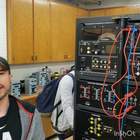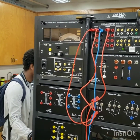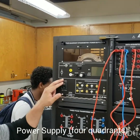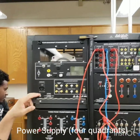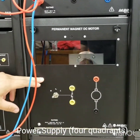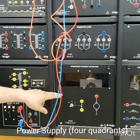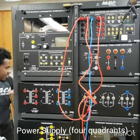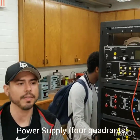My name is Enrique, working on the project with the EE350, and we're going to talk about the 4-quadrant dynamometer power supply to control the torque and the speed of the permanent magnet DC motor panel, right here, where we can create a buck chopper drive, buck boost chopper drive, 4-quadrant chopper drive. We will also be able to do DC motor control using speed current feedback, using the rectifier filtering capacitor along with the transformer.